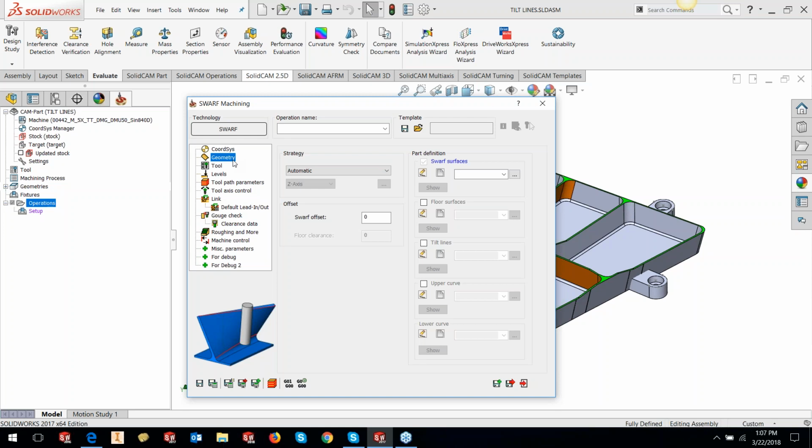We generate triangulation. Now, there are major advantages using triangulation. The biggest advantage is that in triangulation, you get a very reliable result every time you machine a triangulated model. But with a surface, if there are some issues with the surface, if there are deformities with the surface, you can end up trying to do several iterations before you end up getting a pretty good result.